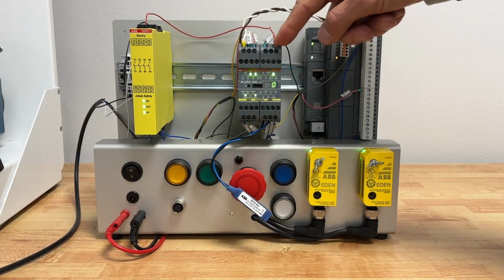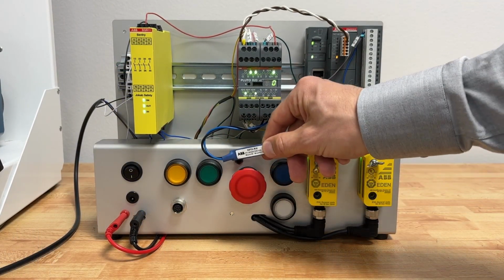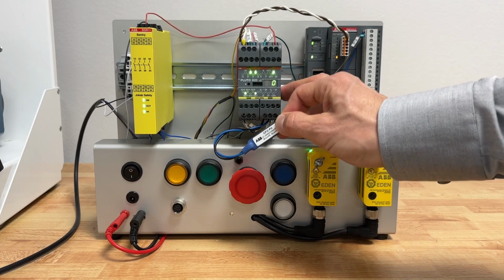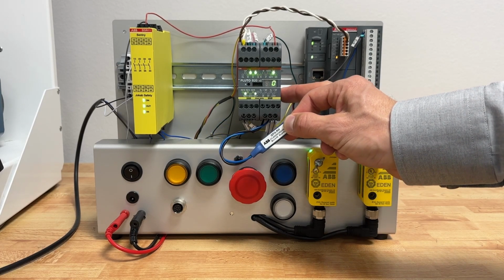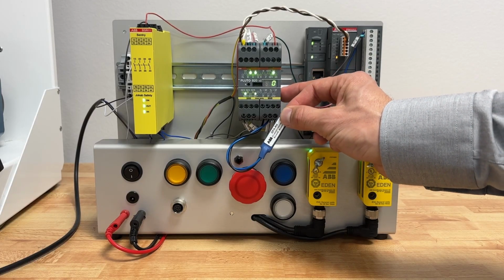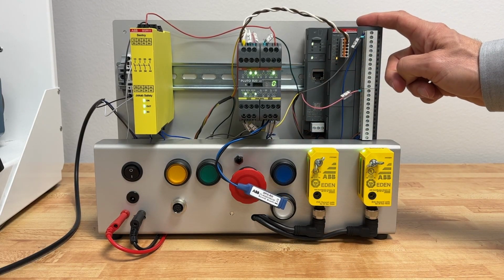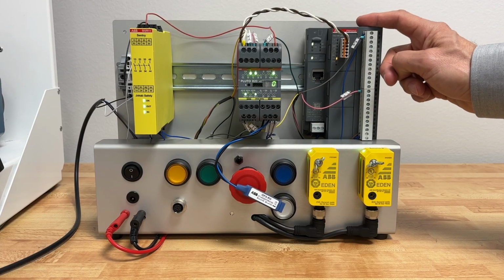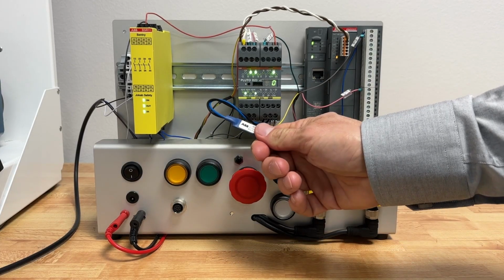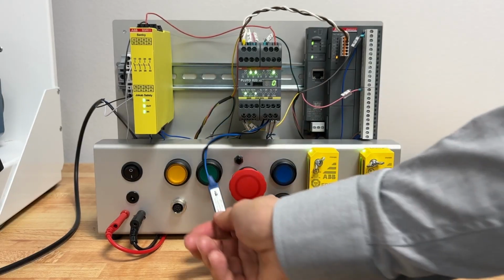The Pluto safety controller is fitted with an IDFix. This IDFix is used to identify the unit on the bus. The bus can be expanded with up to 32 Pluto units, and the AC500-eCo can communicate with each and every one of them. This is necessary to have in a multi-Pluto application.